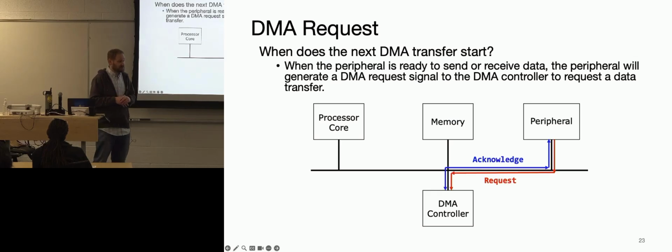like you're trying to measure some sensor, or put a lot of data over UART, or drive ADCs or DACs, or play out audio, right? That's a nice time to use DMA, because now your core doesn't have to keep track of that. You could just have a timer that goes off and says, transfer this data over. It could even be just one value, right? Timer goes off at 44 kilohertz, takes a value out of memory and sends it to the DAC, and the core doesn't have to do anything.